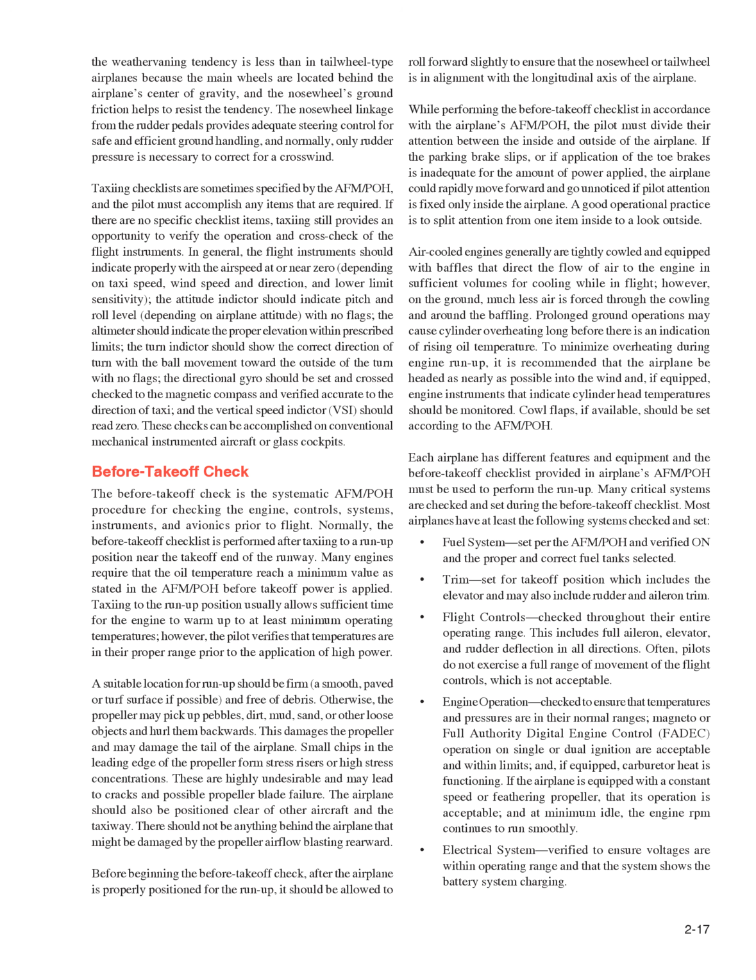If the parking brake slips, or if application of the toe brakes is inadequate for the amount of power applied, the airplane could rapidly move forward and go unnoticed if pilot attention is fixed only inside the airplane. A good operational practice is to split attention from one item inside to a look outside.